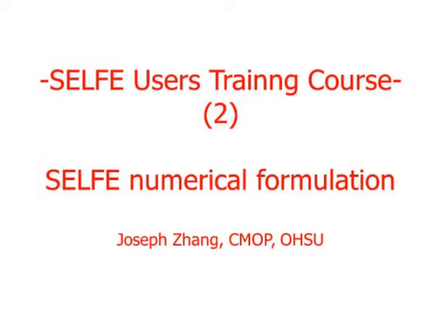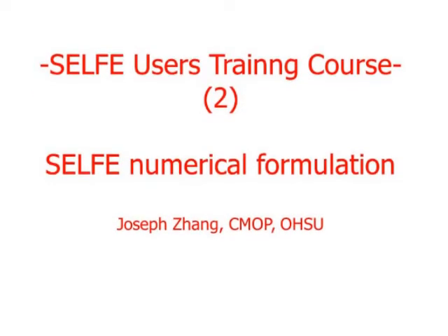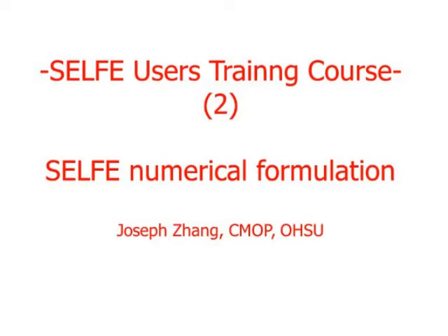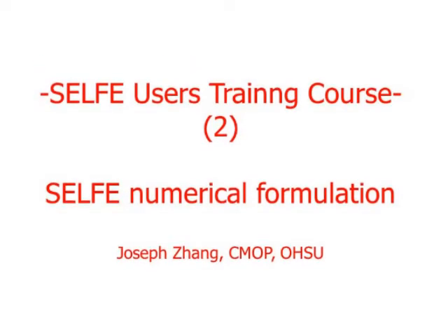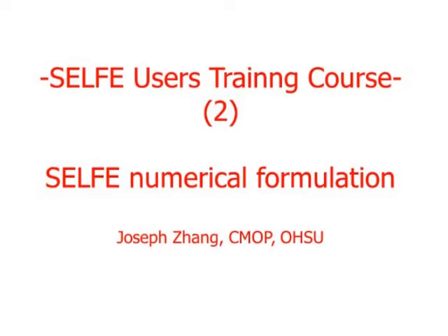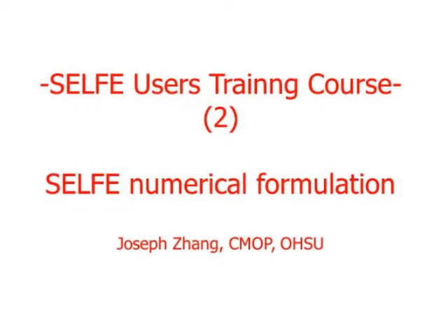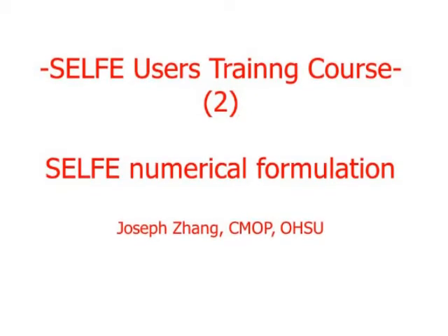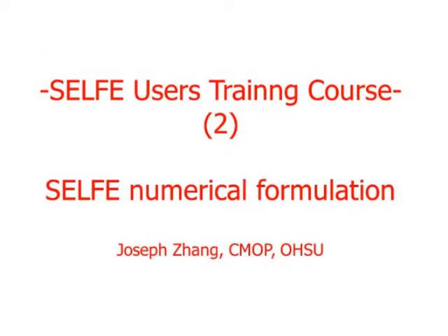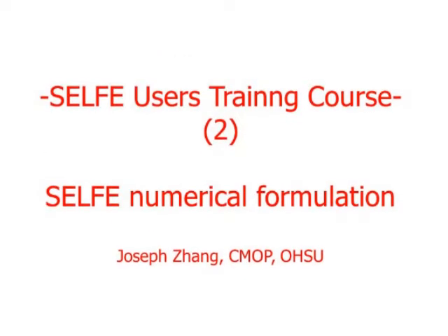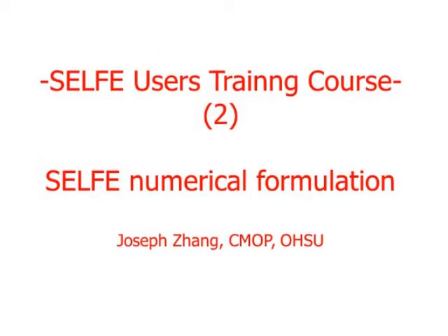Another thing is that in an unstructured grid setting, this stencil may not be well defined. For example, for this internal side, you can see that this side center is outside the quad, so you don't want to apply the filter here.